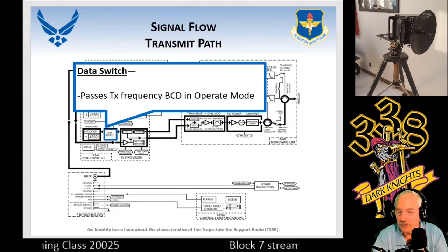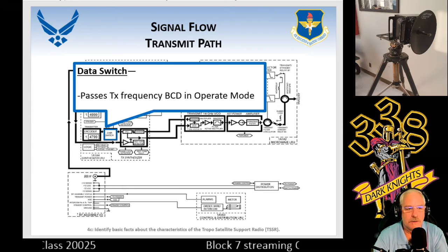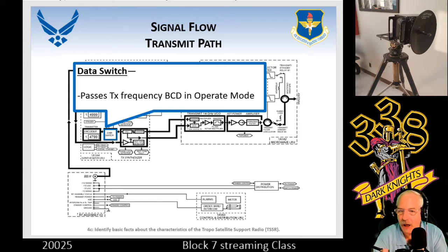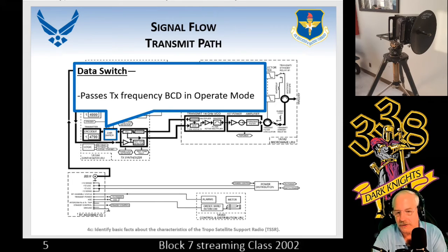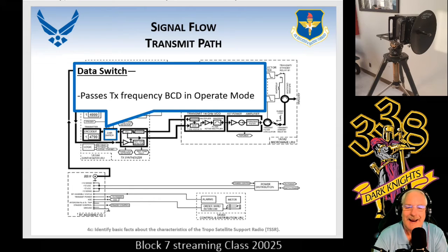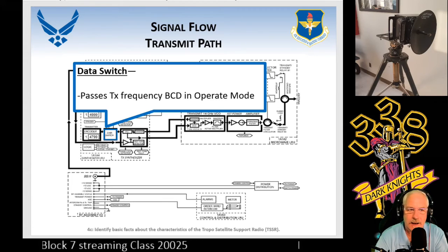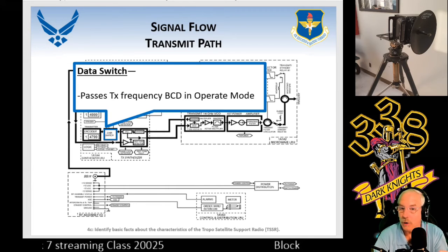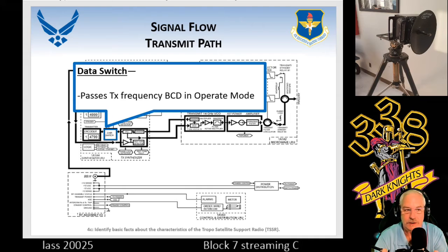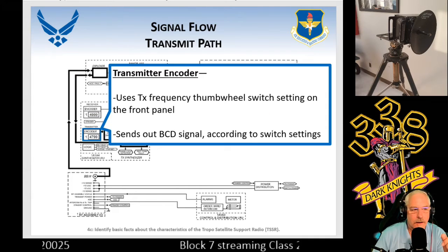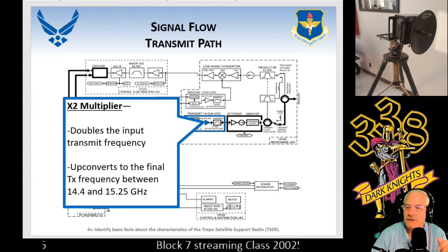The VCO is the actual oscillator, but it sends a sample of the signal to the dividers, and there is a logical mathematical equation. Realistically, it changes it into digital signals, and it counts the pulses. And when it gets to the phase lock loop, it compares that signal with what the encoder is telling it what to do. And if it needs to make that voltage controlled oscillator either go up or go down, it's going to send out either a positive voltage or a negative voltage to keep the voltage oscillator within that frequency. So when we hit the multiplier, it says ×2.